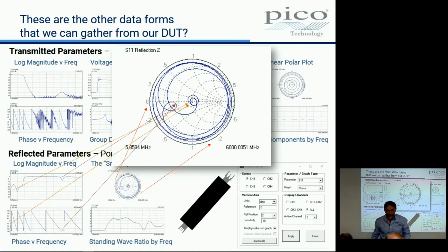It's a polar plot of S11. Well, not quite, but we'll come to that. But essentially, it's the same as that over there. But it's got a grid on it, which is the Smith grid. And we'll talk about the Smith grid in the next talk. So, here we go. We can do the same thing as we did last time. We've got S11 magnitude here, and this is log magnitude, and we've got S11 phase here, yeah?